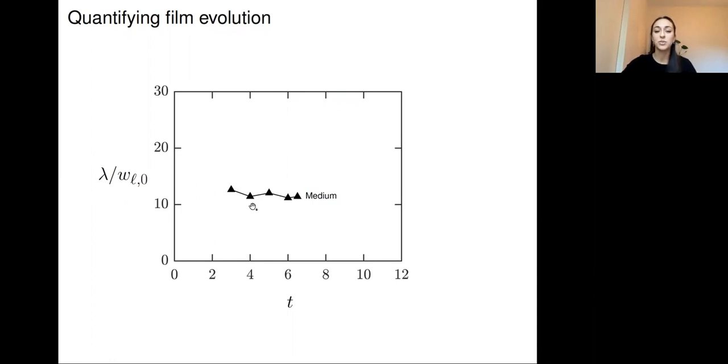And so this points to the idea that those initial deformations are very important, and it is important to get them right, which is part of the motivation of having representative turbulence in that gas phase on that perfectly flat film, such that those deformations are coming out only from the gas phase. Again, comparing the thick film and the thin film, this is also true for the thick film especially. The thin film has a bit of scatter perhaps. These are all from single simulations only. But we see it locking into a fairly constant lambda at late times, especially obvious in the thick film.